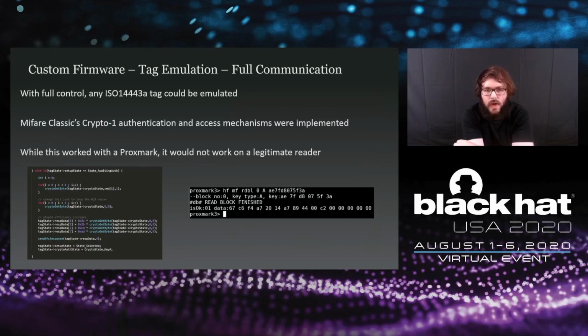With this full control, I could emulate any ISO 14443 tag. I stuck with the MIFARE Classic, but I could expand this quite a lot. The full authentication mechanisms are implemented, which are quite old but quite simple. It authenticates using sort of a standard key, which provides some level of mutual authentication.